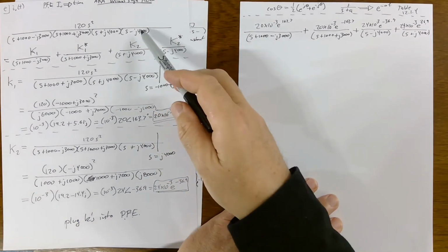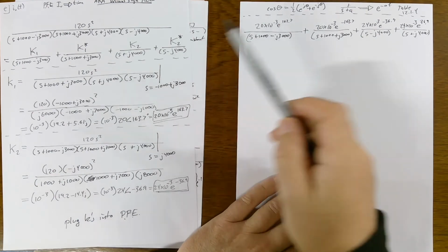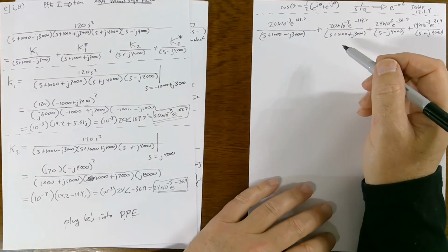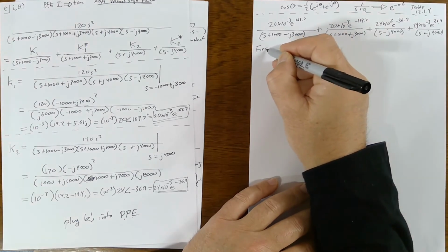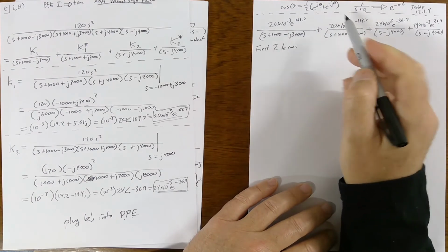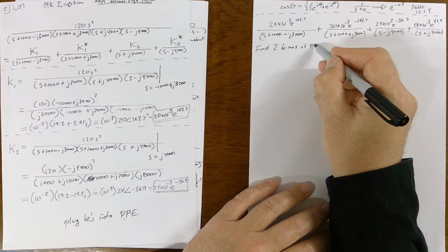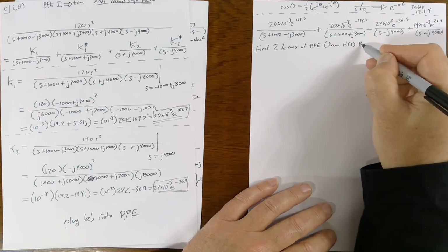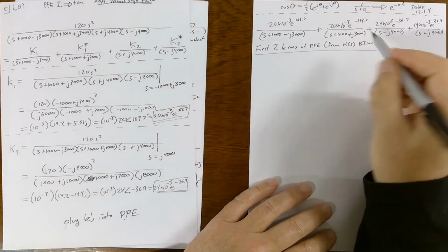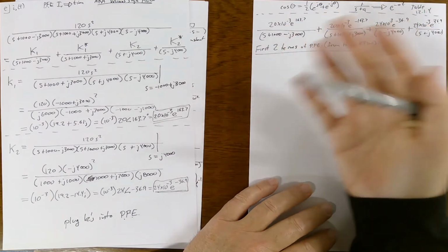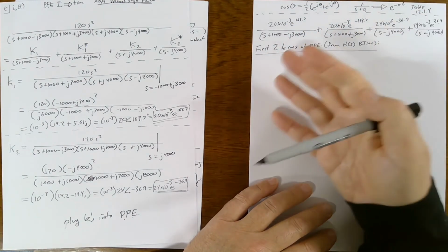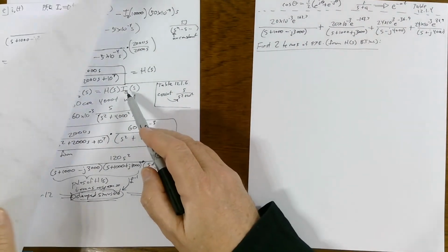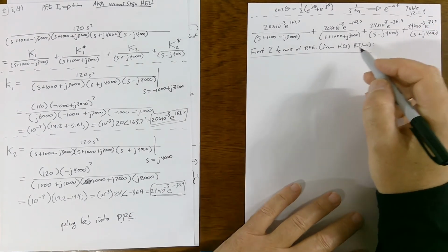So, we did a partial fraction expansion. We solved for the k's and their conjugates. We plugged those k's back into the partial fraction expansion. Now we just need to do some manipulations so that we can go to the time domain. If you look at the first two terms of the partial fraction expansion, those come from H of s. These two terms here come from I sub g. It relates to parts C and D in the solution.